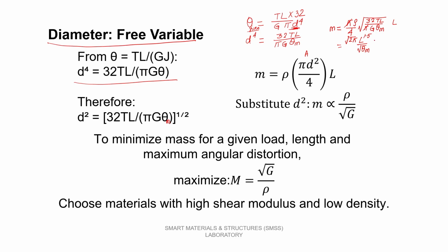So, what is remaining? Let us look into it. Okay. Then there is a torque there. So, torque is the functional part, square root of the torque. So, that also goes out, and then what is remaining for us is the material property, rho by root G. Okay. So, this is the functional part, this is the geometric part, and this is the material property index.